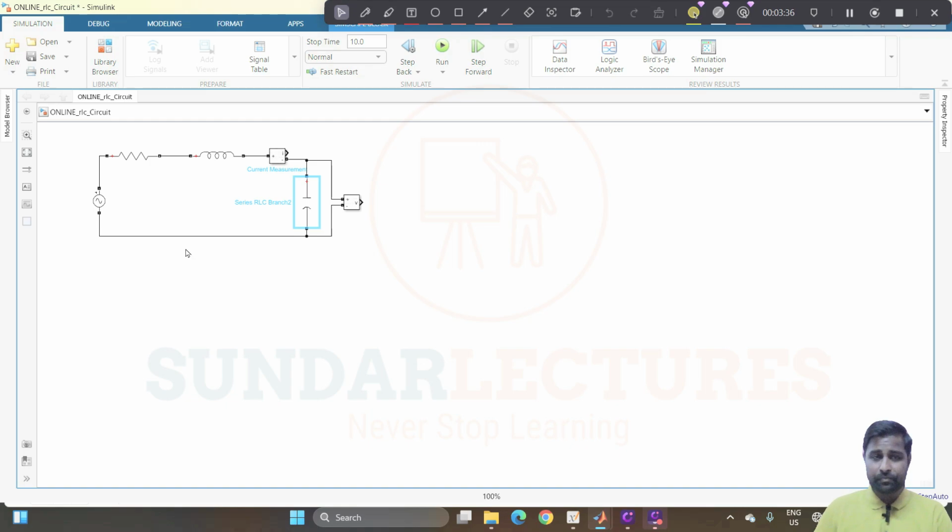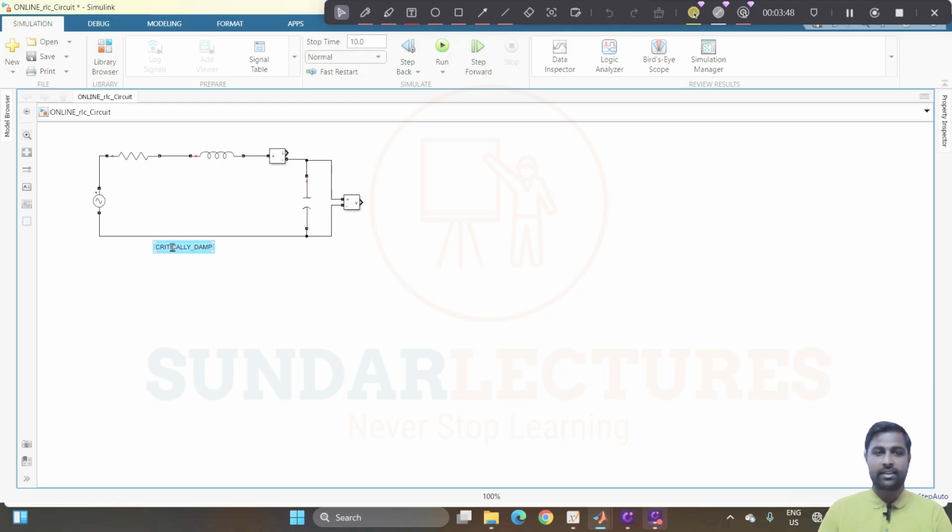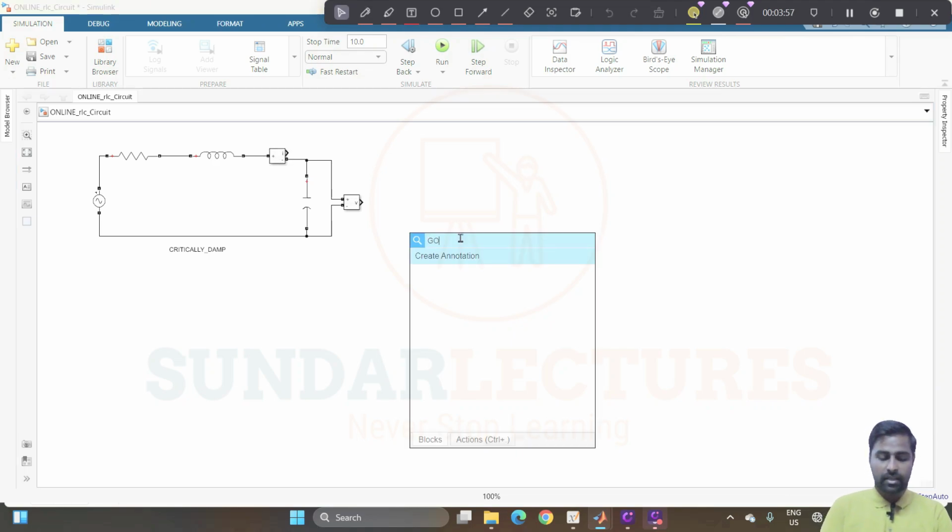We have created the diagram, and you just double click here and type critically damped, click enter, that's all. You can see a text block, and this is critically damped. We have to go again, double click here, get the go to block. I will tell you why we are getting this.